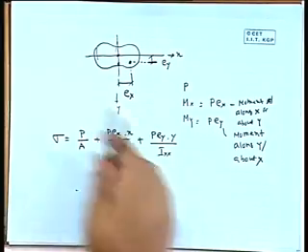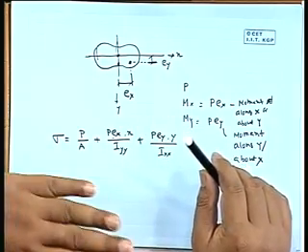So, what will be happening? There will be a uniform level of stress due to P by A, and P Ex x by Iyy. Here there will be a variation of stress along x, because P Ex and Iyy are constant quantities and the only variable is x. So, along x there will be a variation. You can say there is a stress block having a top surface inclined along x, and here it is P Ey y by Ixx. So, there will be a variation like this, right.